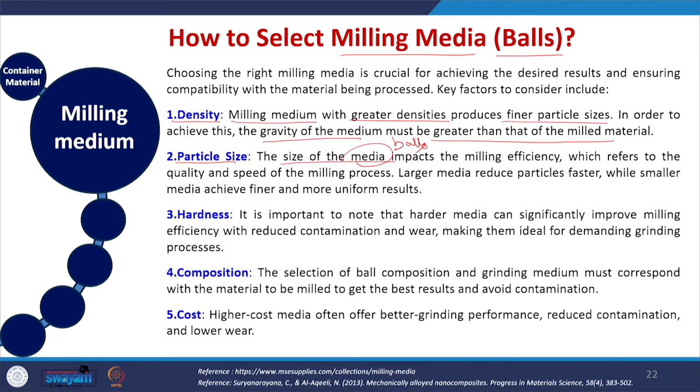If you are using big size balls, they can reduce the particle size faster. And if you are using small size balls, they can achieve finer and more uniform results. So when you are using the big size balls, they reduce the particle size at a faster rate, and the smaller size balls will be helpful for making fine size particles.